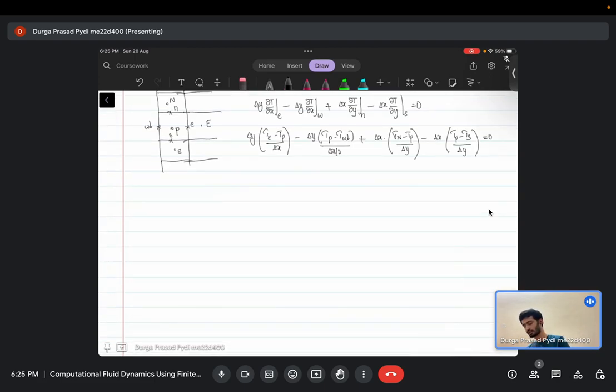So if you group the terms together, you have east comprising of delta y by delta x, and since it is on the west boundary, you don't have any terms contributing from the west coefficient. On the north you have delta x by delta y. On the south you have delta x by delta y. Now you have a source term coming because it's a Dirichlet condition, so that is essentially 2 times delta y T west boundary by delta x. So this is your b term.